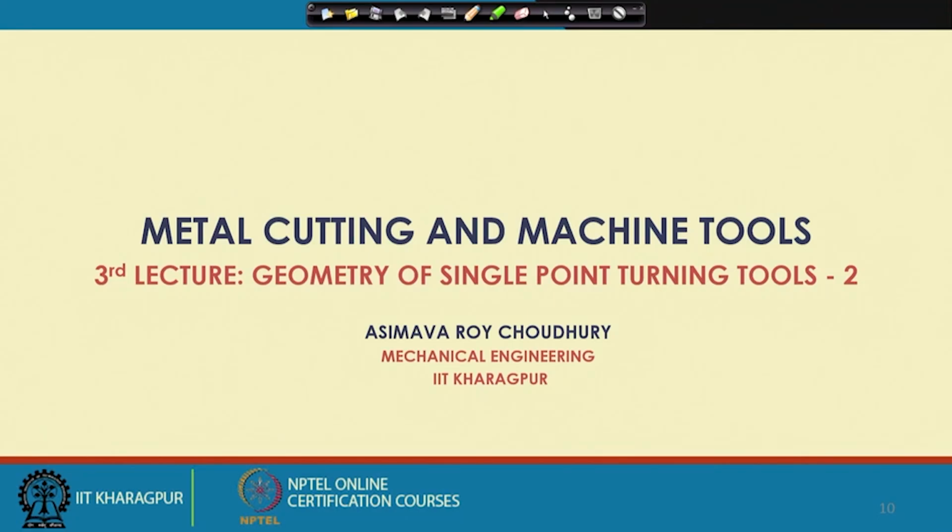Hello viewers, welcome to the third lecture of the course Metal Cutting and Machine Tools. Today we will be discussing more about the geometry of single point turning tools. As you have learnt in the previous lectures, a single point turning tool may be referred to in the tool in hand system, and there we can identify the different planes and edges which are invariant with the orientation of the tool.